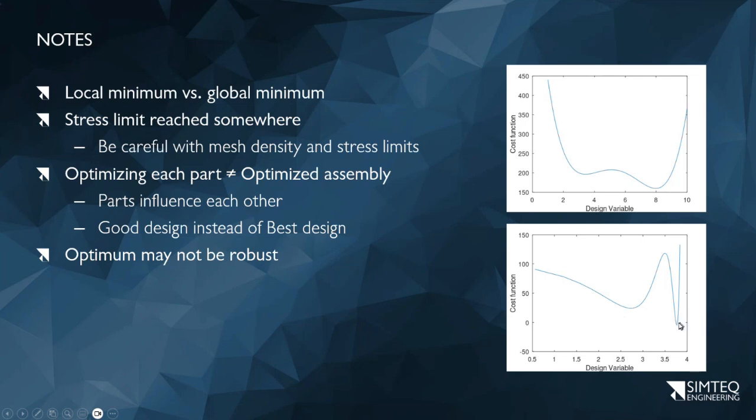If I look at that one, that's a better optimum. But if I change by that same amount, I go from there to there, I jump to those 2 points. So suddenly my manufacturing tolerances need to be a lot tighter if I want to stay in a range close to that. So be careful of just looking at an optimum on its own. It's always a good idea to have a look at what happens surrounding that optimum.